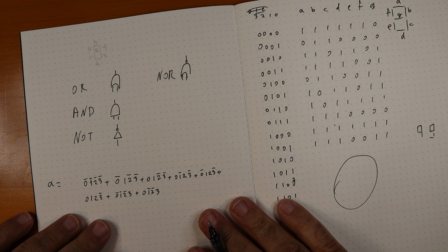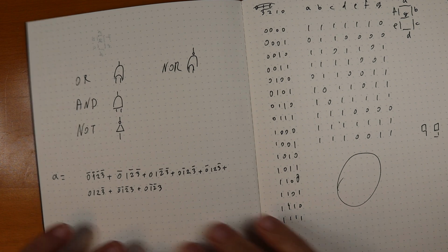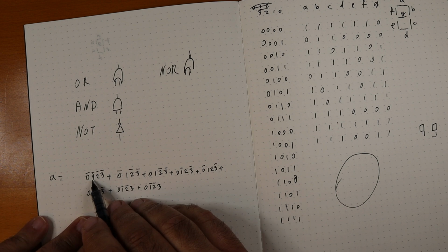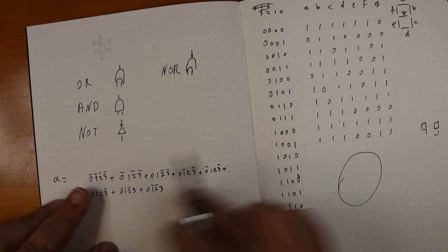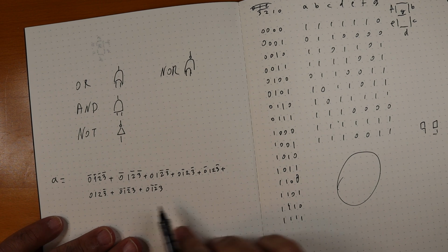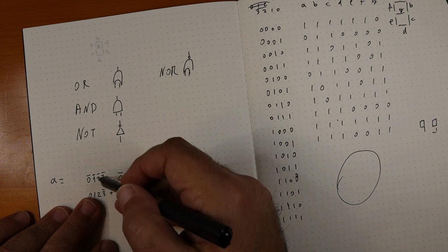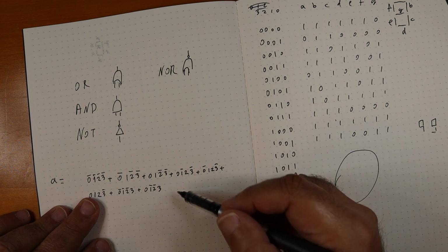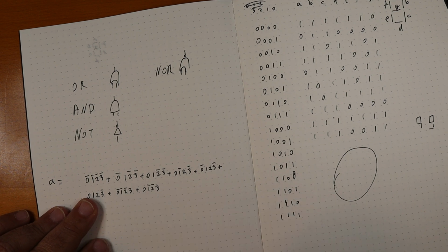Now, once we've written all of that, we can try and reduce the number of gates, because the number of gates we want here is pretty high. Each pair here is an AND gate, so that's 1, 2, 3 gates per tuple here. And we also need, each pair needs an OR gate. So we need 1, 2, 3, 4, 5, 6, 7, 8 times 3. That's 24 AND gates plus 1, 2, 3, 4, 5, 6, 7 OR gates.